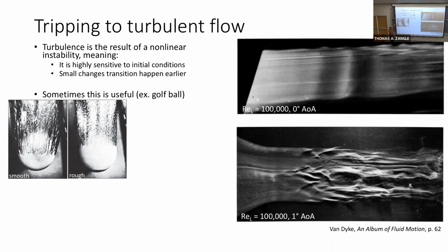And you can see that there's a substantial difference between these two. What you're actually observing here is that in the smooth case, this is the point where the boundary layer is separating from the sphere. Basically, because of the curvature of the surface of the sphere, the flow is no longer able to follow around that curve. And from here on, our boundary layer theory falls apart, and we're creating what's called a wake behind this object.